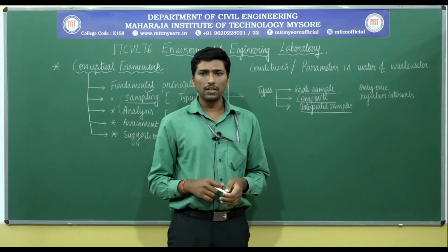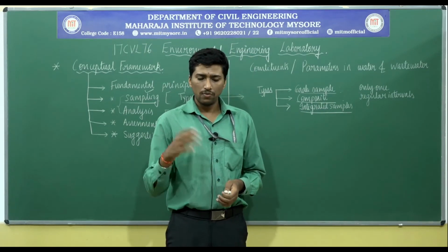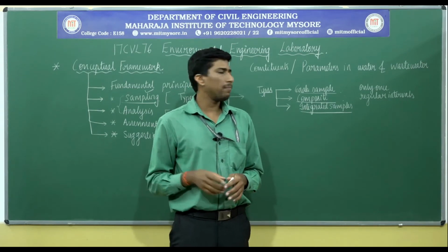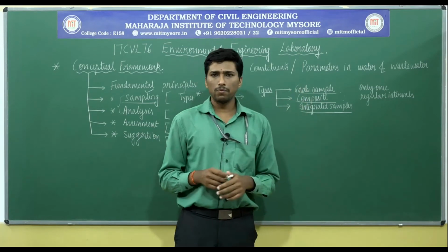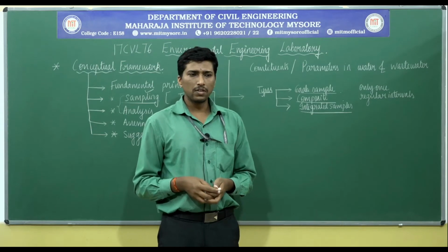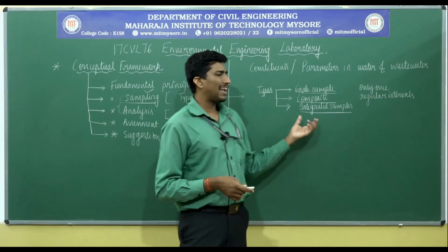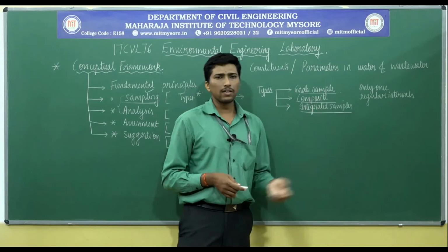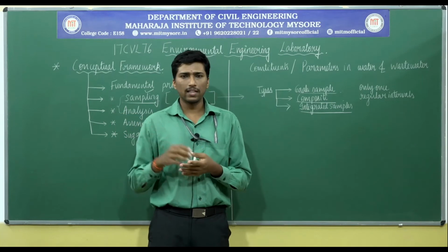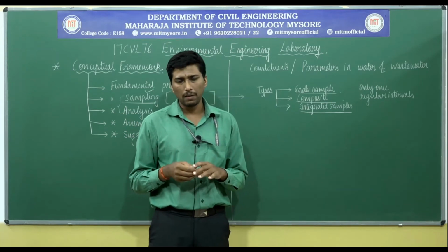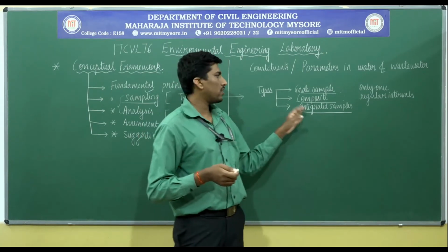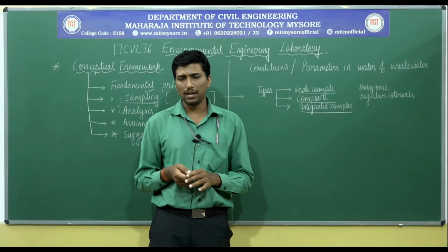The composite sampling has one more feature: you take the sample at regular intervals, that is one thing. Next, integrated sample means a combination of the grab and the composite samples; we call it an integrated type of sampling. This is majorly carried out in the case of lakes. Grab sampling is also carried out for collection of water in canals and the like. Composite sampling is also applicable. If you need precise work, then you need to go for integrated sampling approaches.